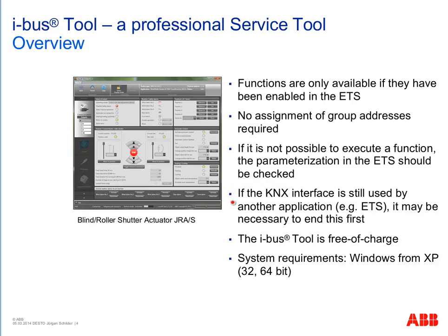But one additional piece of information: this IBUS tool uses the same bus access via the Falcon driver, which the ETS also uses. So it can happen that you get a communication conflict. That's why we recommend at first close the ETS, start the IBUS tool, check your KNX device via the IBUS tool, and then close the IBUS tool and start the ETS again. Never run two software systems which use the same Falcon driver, like the ETS and the IBUS tool, at the same time. Very important.